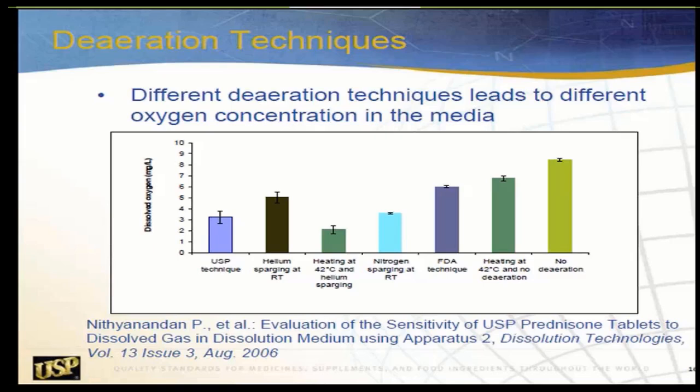But please remember that when you sparge something with nitrogen, you're replacing air, especially oxygen, with nitrogen. So taking a dissolved oxygen measurement of nitrogen is a little bit meaningless, because it's going to be very low in dissolved oxygen, but it's going to have a tremendous amount of bubbles in there from nitrogen. In other words, if you used a nitrogen sensing probe, you'd probably see it's off the chart because it's saturated with nitrogen.